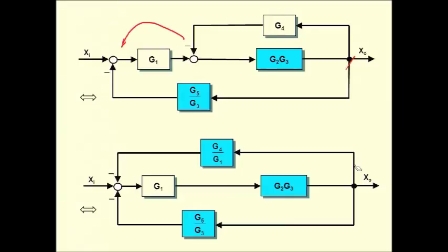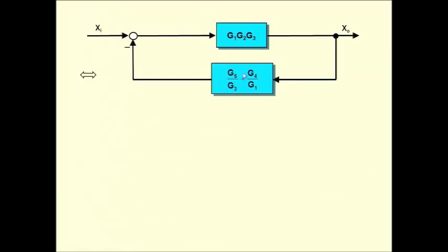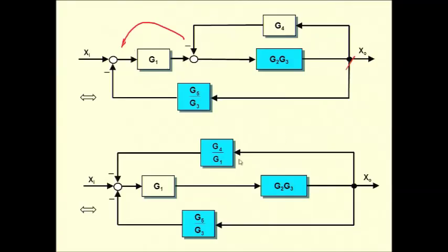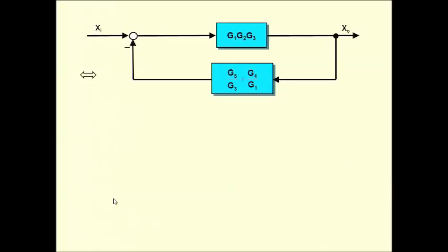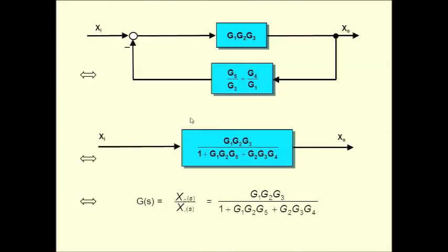Then I noticed that there are two feedback paths that can be combined because they are in parallel, so turn it into one feedback path. And this time I'm preserving the fact that it's negative feedback. So what I'm doing is adding these two blocks together and keeping the negative of them. Then I'm applying the standard rule, G over 1 plus GH. Yeah, questions? Nope. Okay, next one.